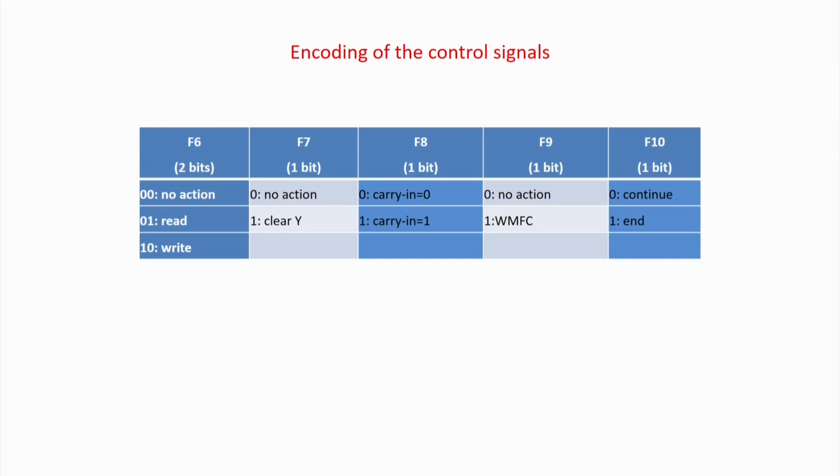And there were some other control signals, as I told you, that there is something called read. Again I am putting the read in a single cluster because the memory can be read or write at one go, and similarly this is the carry in, you are putting in one cluster because carry can be either 0 or 1 and so forth. That is wait, because wait can be simultaneously 1 with anything else, so you can put it in another cluster. So these are some of the other control signals for the memory and wait for memory cycle, etc.